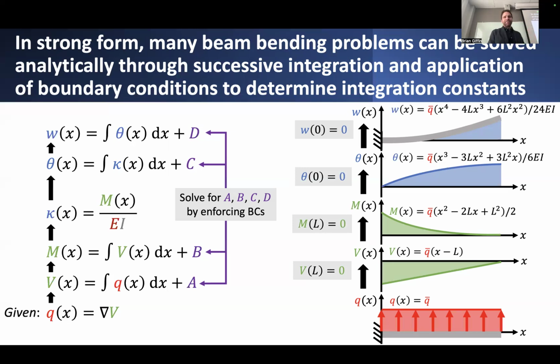So it turns out that this ends up being a 4th order polynomial. If I started out with some polynomial of order n, let's say, then the deflected shape is going to be some polynomial of order n plus 4, because I have to take 4 integrals. It's a little bit of work, but once you get it, you basically know the deflection everywhere through here, and all these other functions along the way. So you can take, at any cut section, what's the internal moment at this section, or things like that. And it also makes visualizing and figuring out where is the maximum shear force, max moment, max rotation, tip deflection, all those things, a relatively straightforward thing to determine.